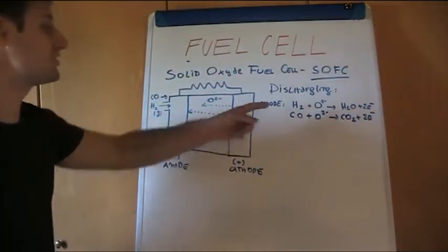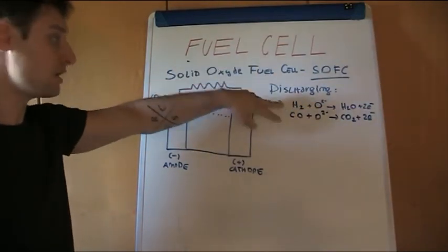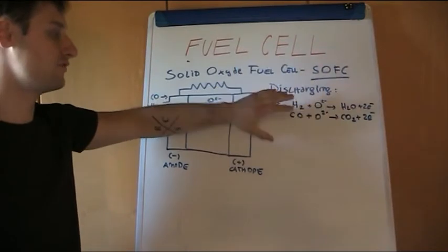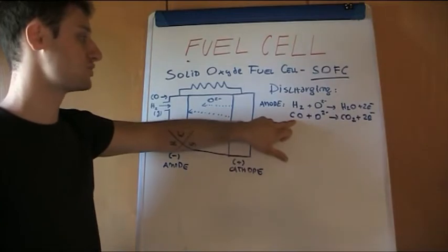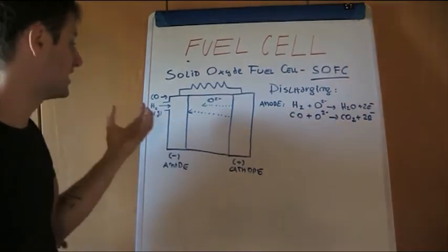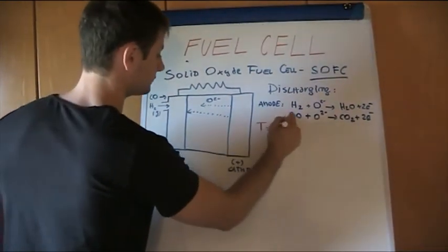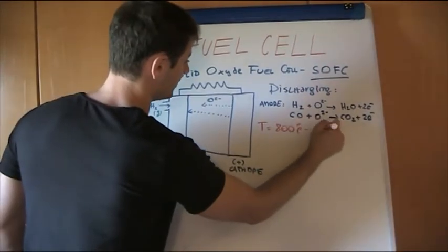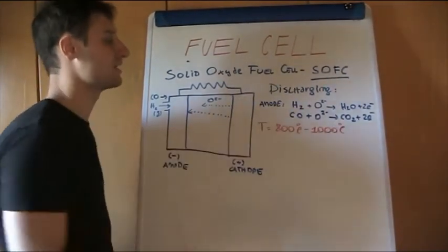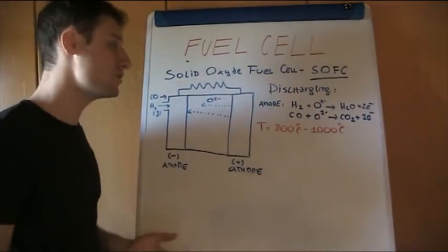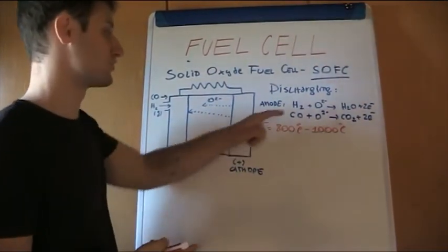So we can have this oxidation or these oxidations, or if you're using syngas, both of them, or also if you're using some hydrogen that is impure, we can have even the conversion of CO. Since we are working at high temperature, the adsorption energy of these species on the catalyst is reduced, and so we have no poisoning problems, concerning both CO2 and carbon monoxide.